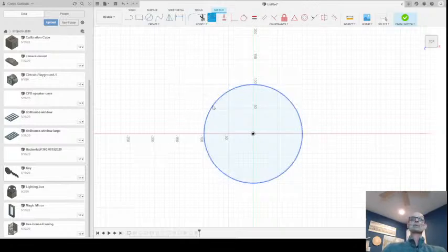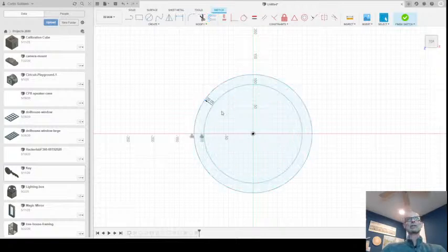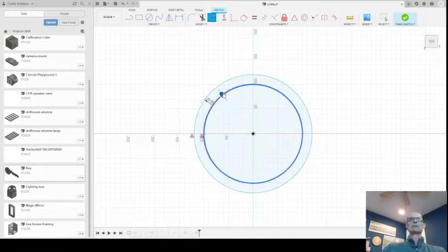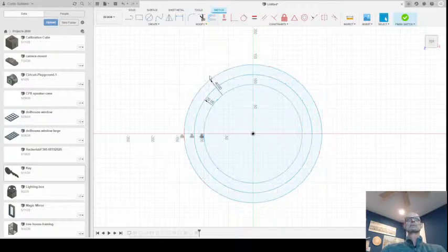You click that, we can click this line, and now we can create a second line that's offset by a certain dimension from the first line. And these can cascade. You can do multiples of these. So I can say 20 millimeters, and then back to modify, offset again. And this is going to be 40 millimeters, and so forth. So let's finish that sketch.